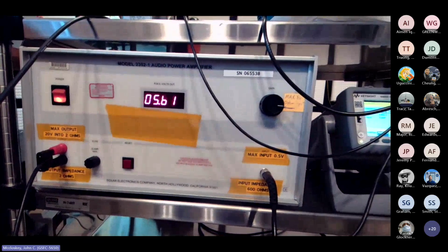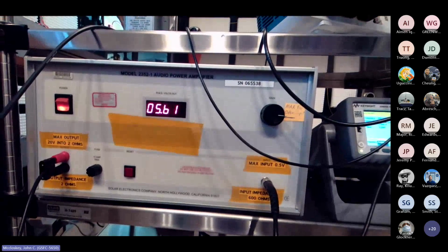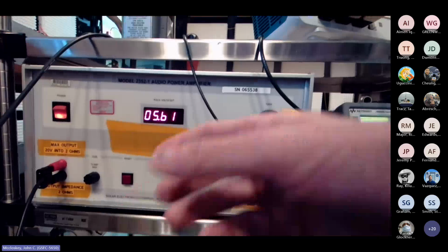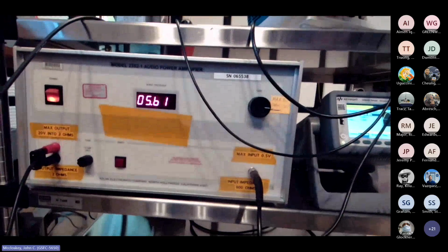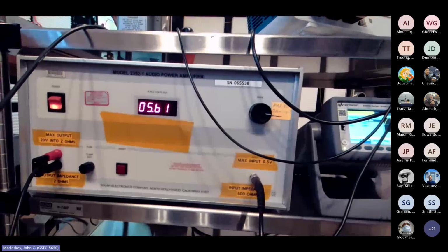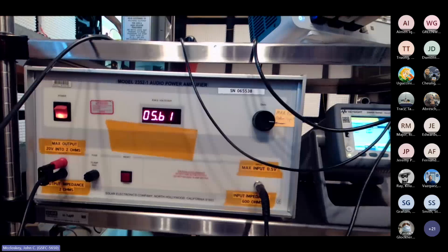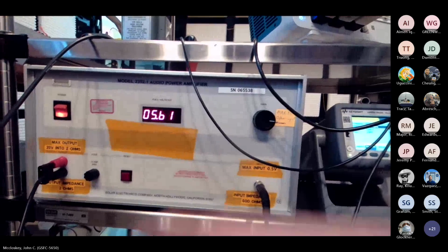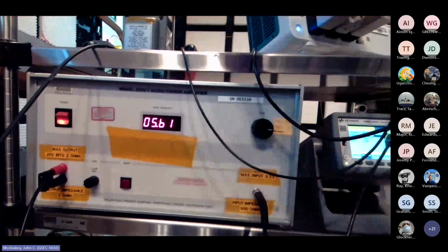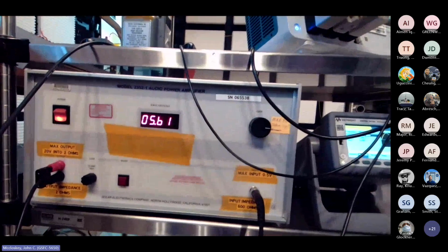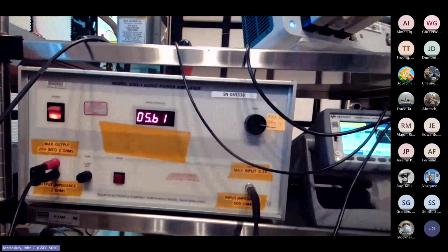Okay, so we pre-calibrated to get 1 volt RMS across our half ohm load, but it referred to the transformer secondary. There was a half ohm source impedance when we did that. So our open circuit potential should have been about 2 volts RMS. So this is telling you that due to any number of factors, probably transformer inefficiencies, among others, we're having to drive the amplifier a bit harder.